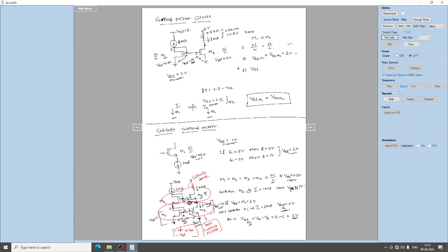So here, what is the base current mirror? The transistors M2 and M4 act as a base current mirror because all the three conditions are satisfied. W by L are same, VGS are same, and VDS are same. It is an exact current mirror. Whereas M1 and M3, we cannot say that, because anyhow the W by L of M1 and M3 are same and VGS of M1 and M3 are same, but the VDS of M1 and M3 depends upon the load that we connect to the cascode device, the transistor M3.